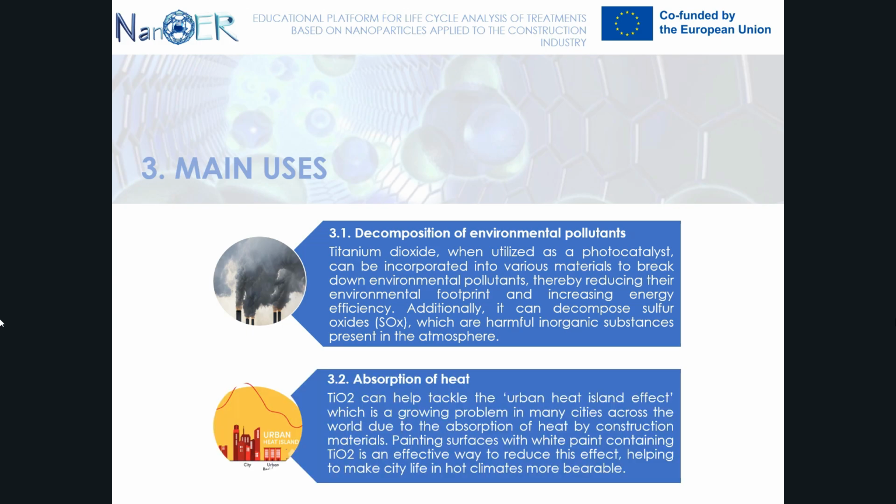With regards to absorption of heat, TiO2 can help tackle the urban heat island effect, which is a growing problem in many cities across the world due to the absorption of heat by construction materials. Painting surfaces with white paint containing TiO2 is an effective way to reduce this effect, helping to make city life in hot climates more bearable.